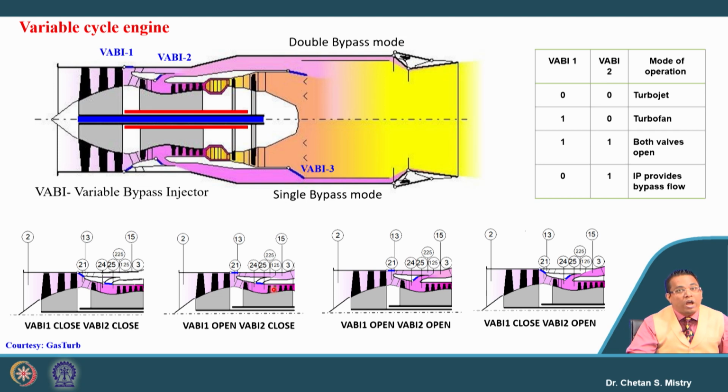In order to generate the same power to run this compressor, we need to increase the velocity at the entry of the turbine. It is called a variable area nozzle vane. By changing the area between the nozzle vanes, we are able to increase the velocity of the exhaust gas, and that will strike the rotor of the turbine and generate the same power as per the requirement.